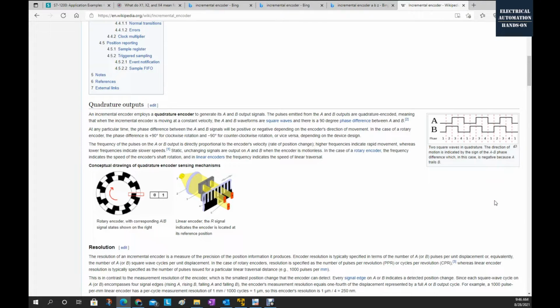To count the actual signals, one channel is enough. We can use the rising edge to count how many counts come from this signal. The reason the incremental encoder usually gives us 2 channels is that A and B can give us a direction. If A is behind B, maybe that represents forward. If A is at the left side of B, the system will know you are doing reverse.